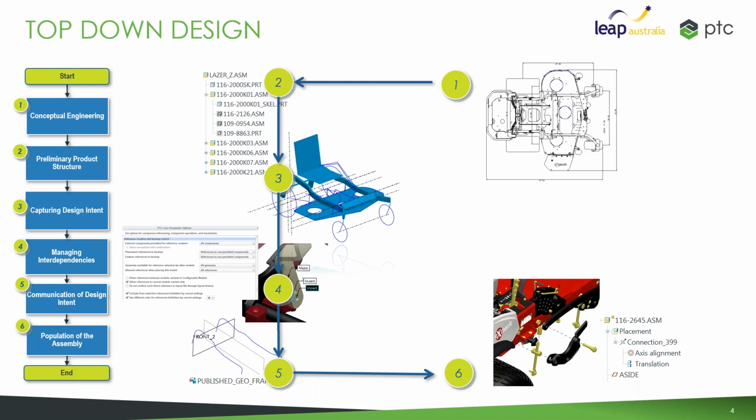The very first thing in this list is the top-down design approach. Creo offers a 6-stage top-down design process for assembly design. In the beginning, designers can use conceptual tools like Creo Layout to lay out the design, make the space allocation, and capture the design intent. At the second stage, we create the initial structure, which is the foundation of the design, so that we can plan the design ahead, which is very critical. In this process, even an empty part is enough, and there is no need for any geometry in it. The benefit here is that it can be managed immediately in PDM systems like Windchill.